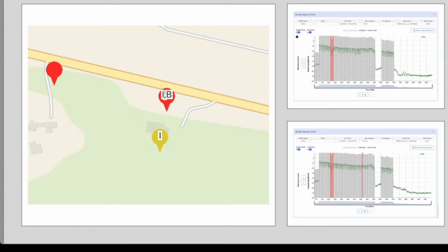And the other thing that we see with both of these modems, going back to the slide, is that there's a suckout just above, I think it's 200 megahertz there. So we see the same suckout in the top slide and the bottom slide. Yeah, so we see the same suckout on both of these subscribers' homes.